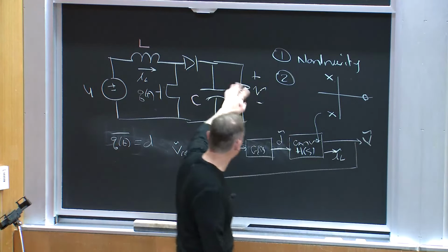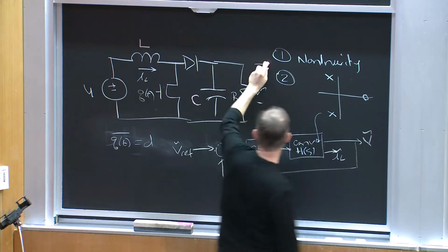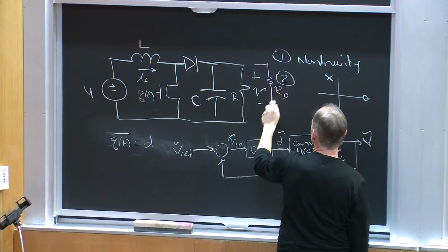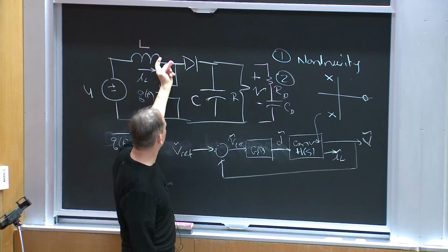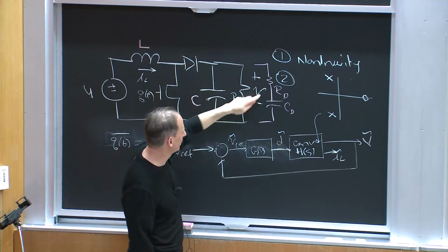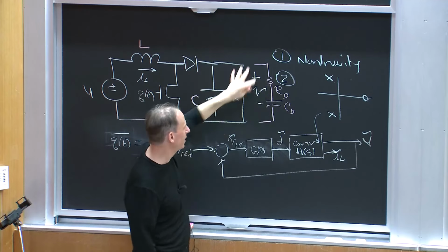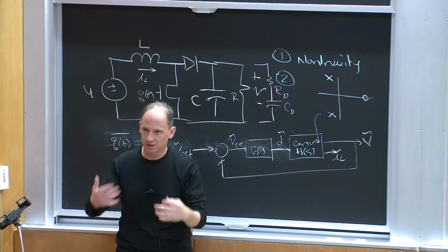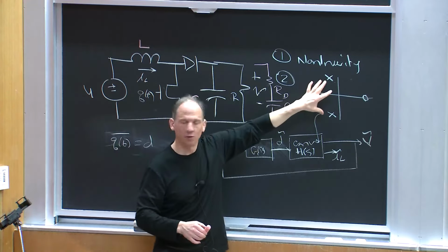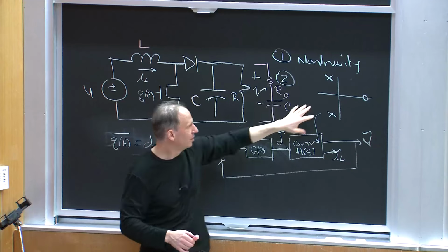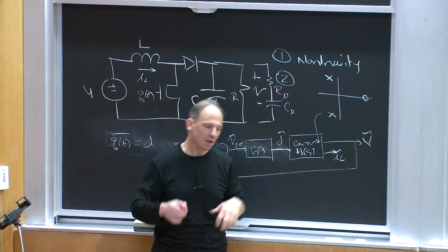So we said, oh, it's this resistor that's damping the poles. Maybe I could go add RD and CD, such that CD is a short circuit near the corner frequency where the L and C are oscillating, so RD serves to damp it, and RD doesn't vary. So by picking additions to my plant, by changing my converter, I can help make things better damped and maybe get better pole locations here. I'd have another pole location, but maybe it would be a low order, sort of overdamped pole location. So that's one thing I can do.